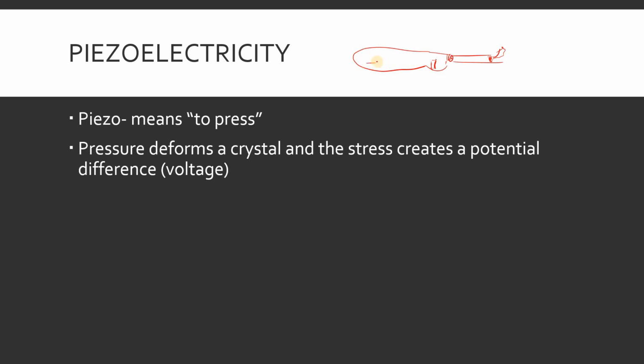For the most part, that's an almost perfect picture. Of course, usually there's a little line over here that lets you see the fuel, but right about here there's a little triangle that bends inward. And remember, electrons concentrate right here. There's a little tube that goes inside, coils around, goes in here. The piezoelectric crystal is here, so when you push in the button, you put just enough pressure on the crystal, it charges this, and the electricity forms on that triangle, sparks the gases, and you've got a flame.